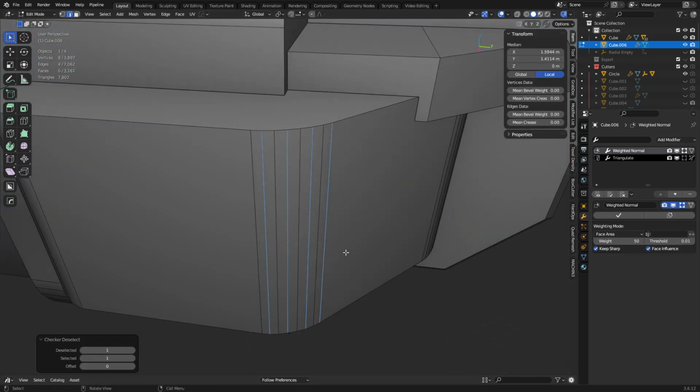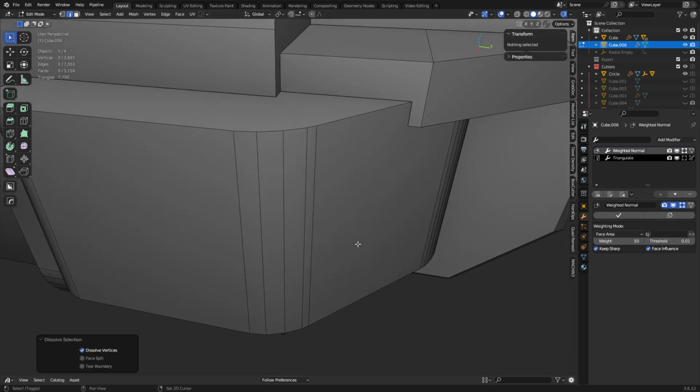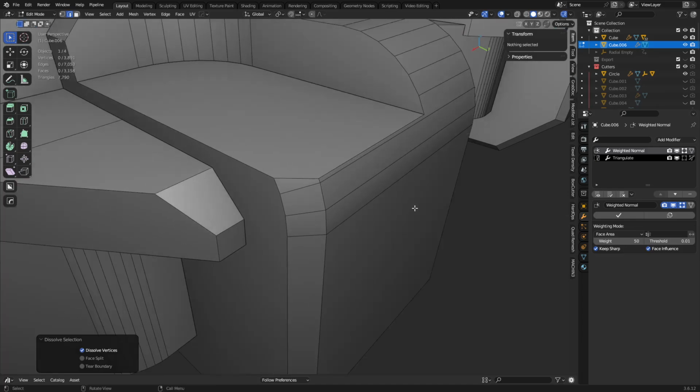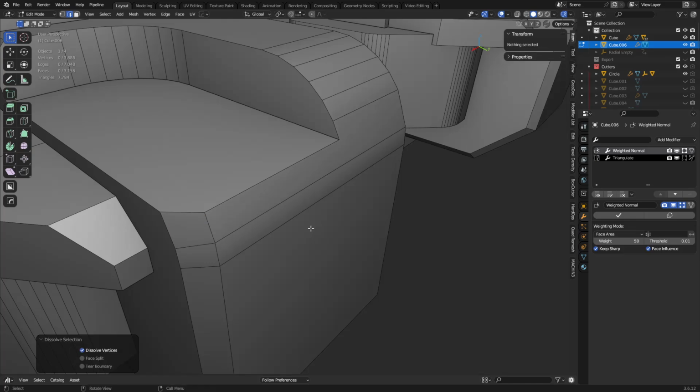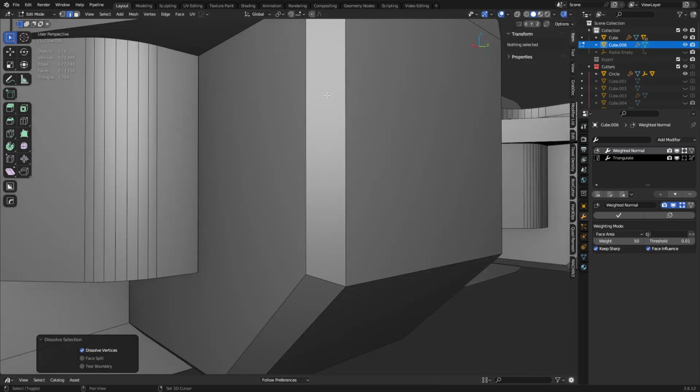This is why you want to do certain bevel segments as well. I've talked about that on the channel. You want to do like 2, 4s, 8s, 16s, 32s. And that's so that you don't run into the situation where you don't have a center edge, basically, that you can get rid of also things like this. You might slide them a little before you dissolve the other one, right? Just balance it out.